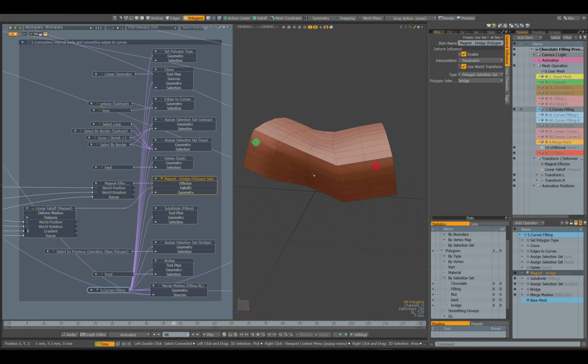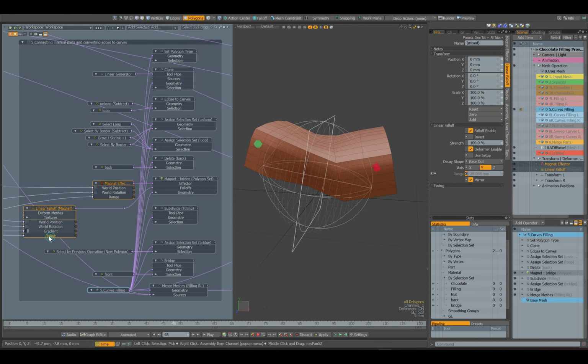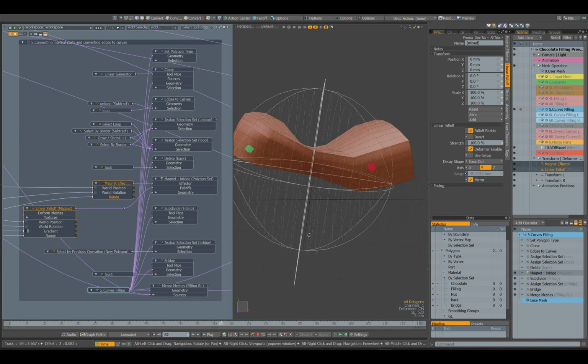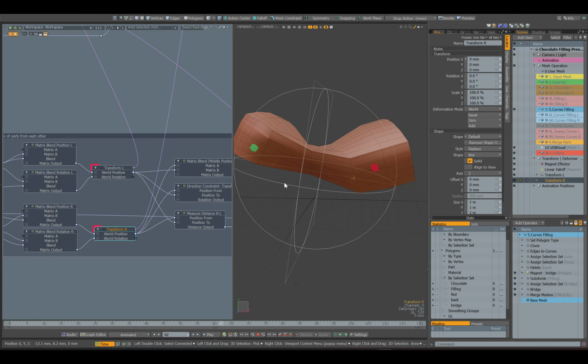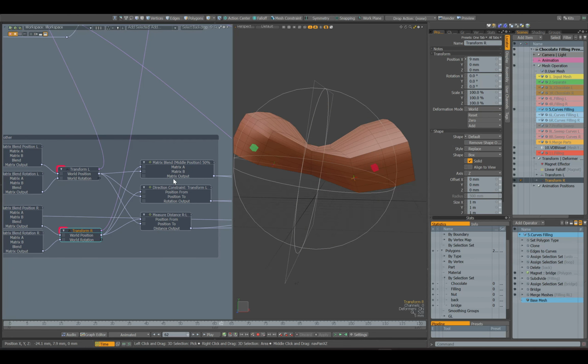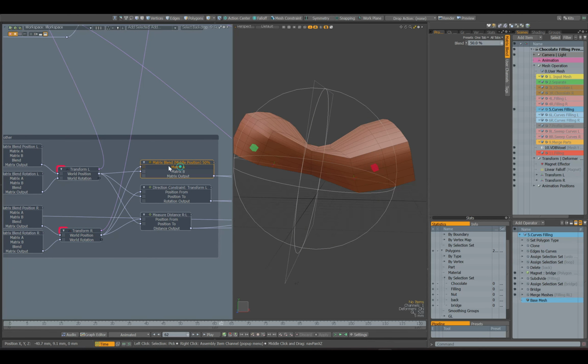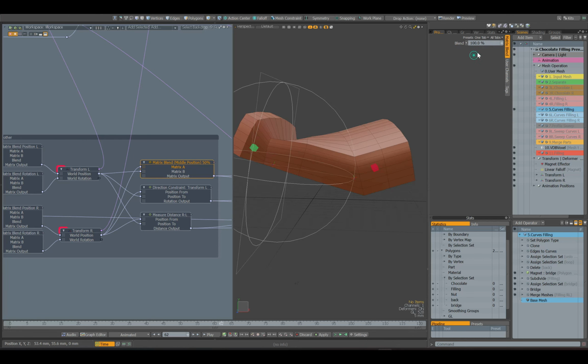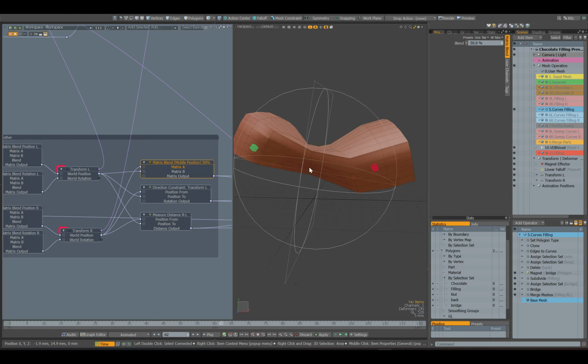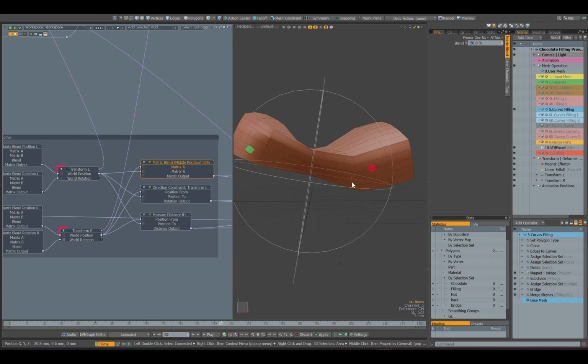To place the deformer and falloff in the middle and specify the value of their range action, I used a node that calculates the distance between two objects. These are the locators of the deformer's transform nodes. I connected two locators to the matrix blend node to find the middle position between them. In the matrix blend node I set 50%. This will be the middle position between the locators.